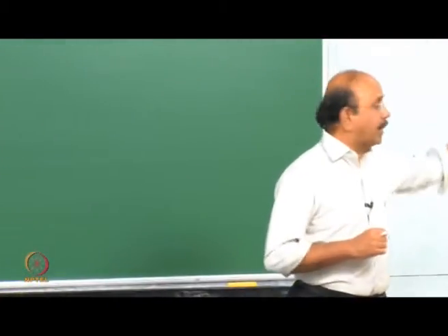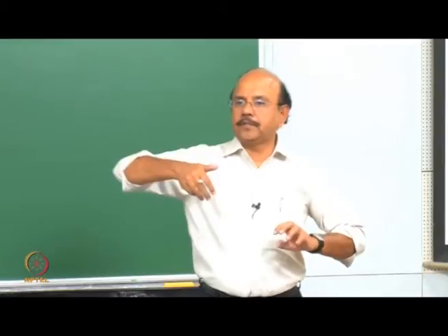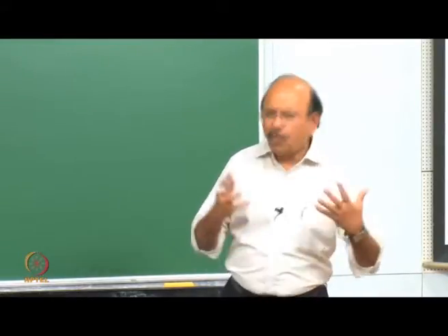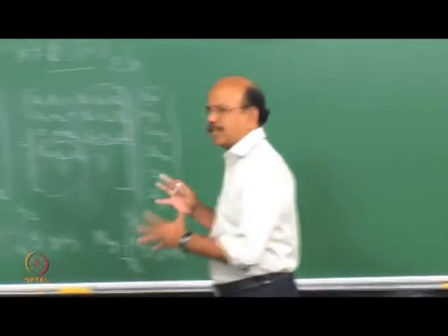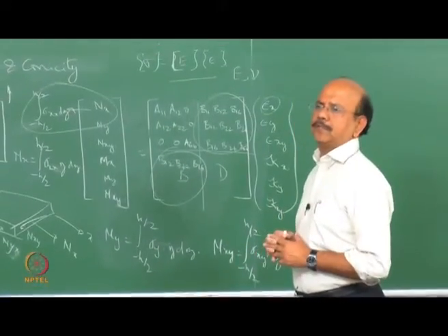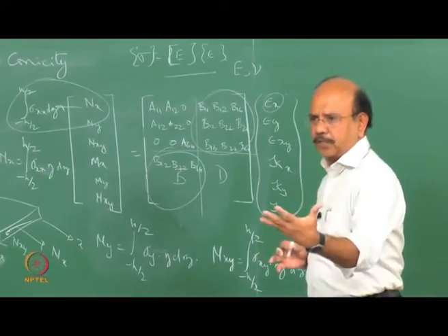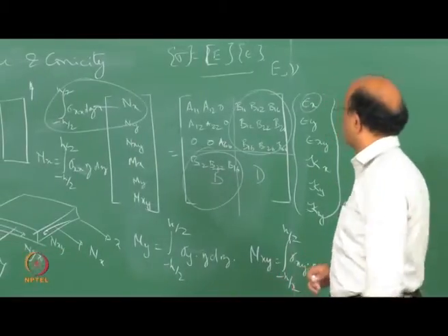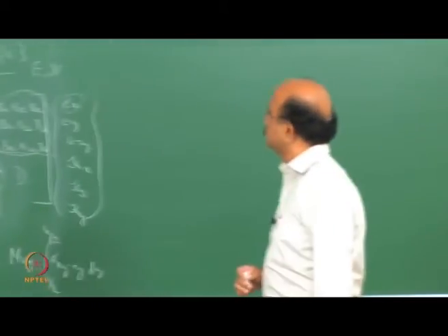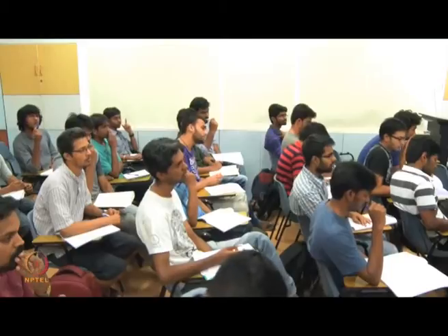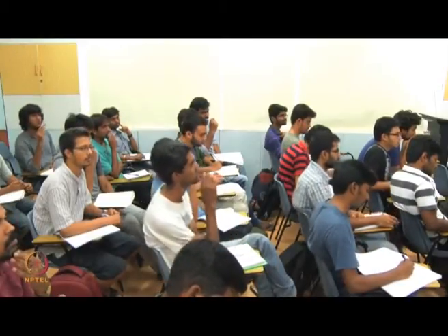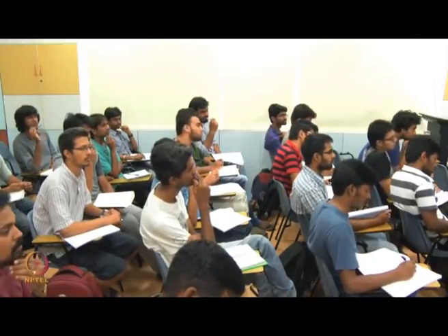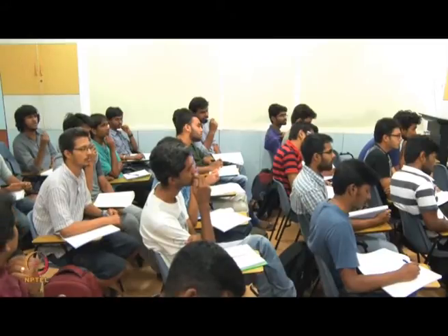Okay. So, in other words, that's what happened here when I stretched, twisted, and so on. How do I apply this? Why are we talking about this? Changing curvature gives rise to a force. Fine. So why am I worried about it? If the tire, even though the vehicle moves in one direction, because there is deformation in one direction, there will be a reaction in all three directions as well.